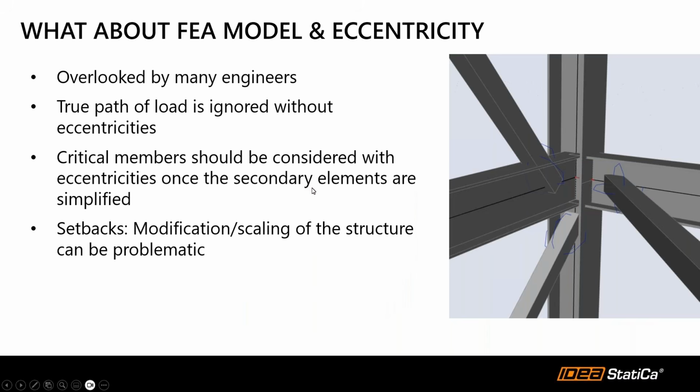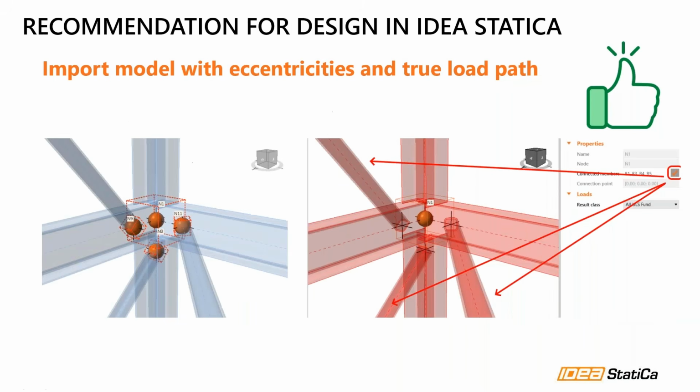But is it necessary to consider the eccentricities if you would like to use IDEA StatiCa Member? Yes, it is. Because if you import it with the eccentricities, there is a true load path on the structure, and in the IDEA StatiCa Checkbot, we enable you to merge the nodes into one single node, but with consideration of the eccentricities and the additional internal forces that exist due to them.